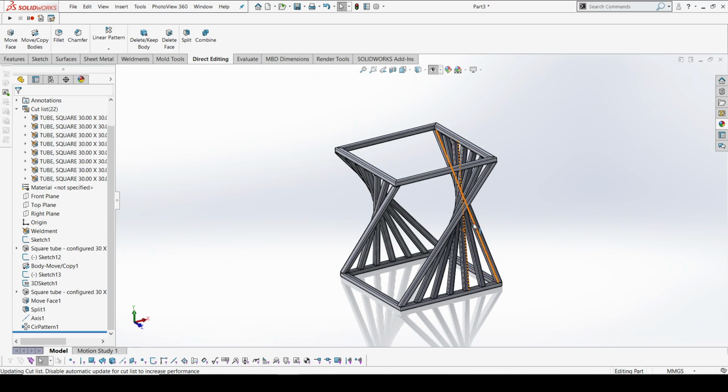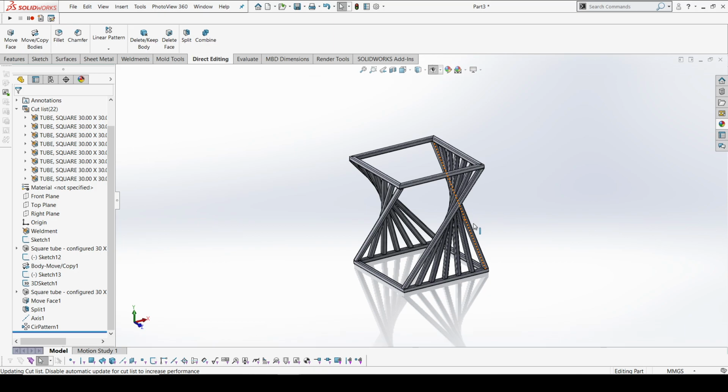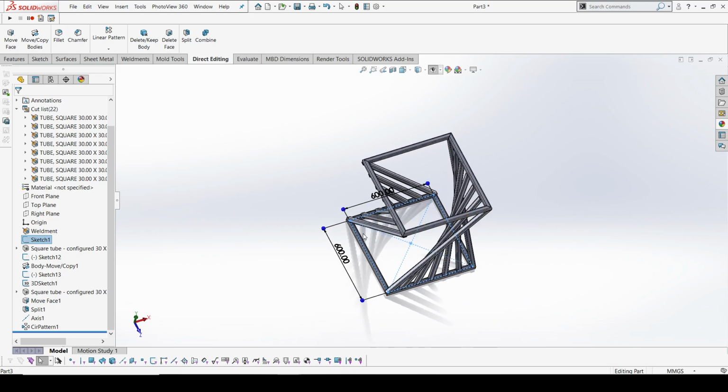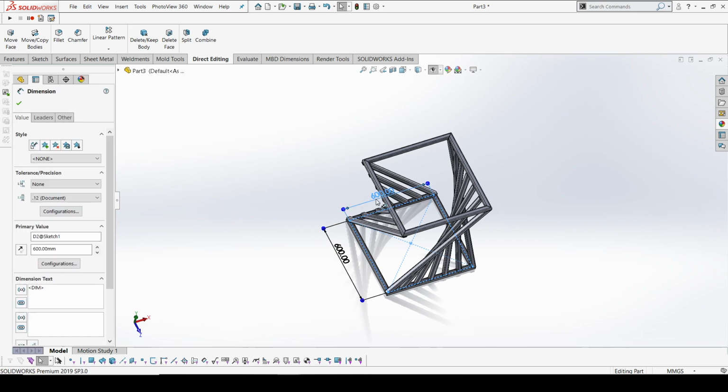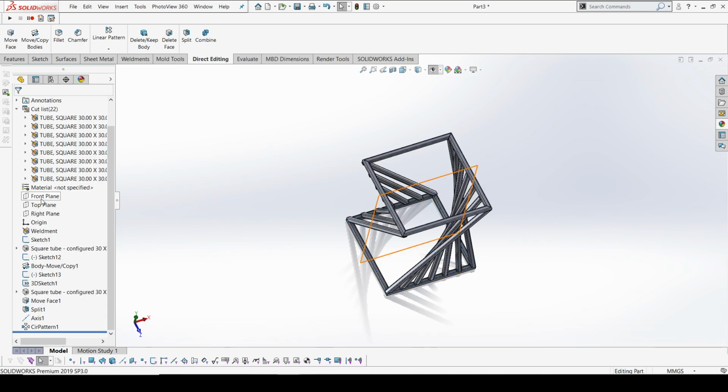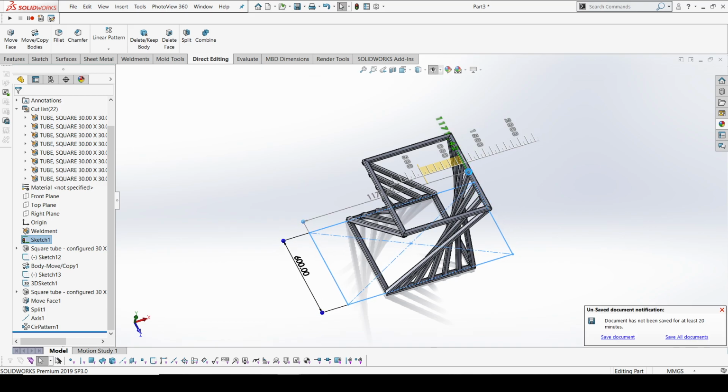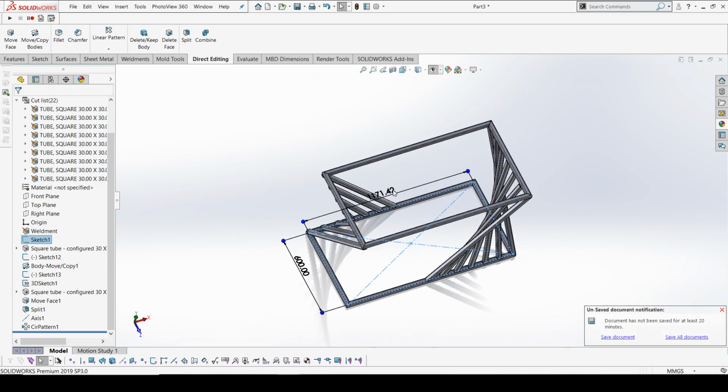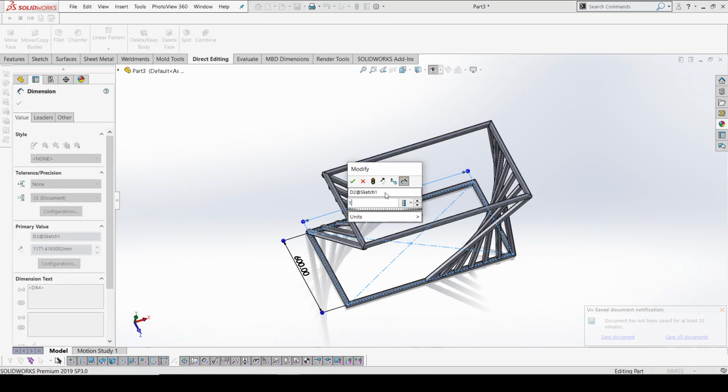Now I'm gonna show you the same process can be done by increasing the width, I mean the length of the table. For that I'm gonna select the sketch. Yes, here, and we cannot change the 600 since we have created points for 600. Eventually we have distributed by 200, and we have created 7 points, but we have the option here of increasing this length, overall length, I can say, or you can just drag it by selecting this however you want. Exactly. So yeah, you can double click and make 1200.